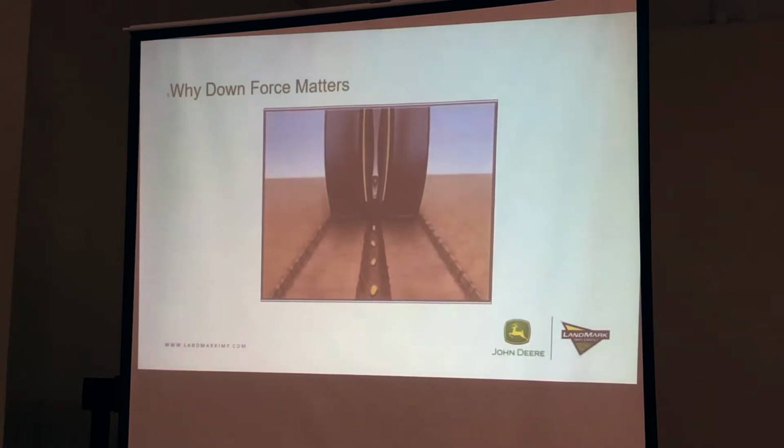It's important to remember while setting downforce to set enough but not set too much. The amount of downforce needed will vary from field to field depending on your field conditions, varying on your amount of tillage, whether you're no-till, crops you're going through.